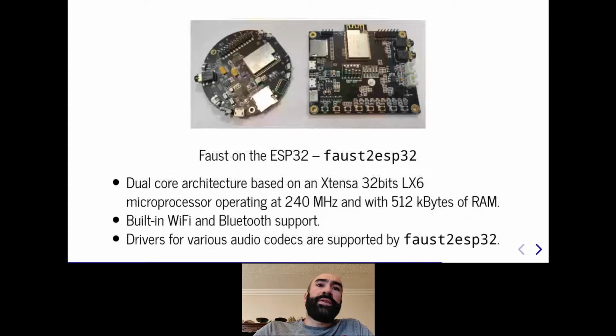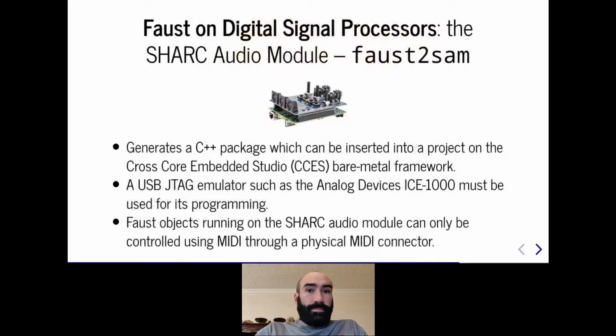Additionally, the LilyGO TTGO TAudio can now be fully programmed with Faust without writing a single line of C++ code or Arduino code. In that case, metadata can be used to access the various analog inputs and GPIOs of the board, and that's what we do in the case of the Gramophone. If you never heard of the Gramophone, just visit the Gramophone website, and you should be able to find it very easily. It's programmable musical instruments, programmable with Faust.